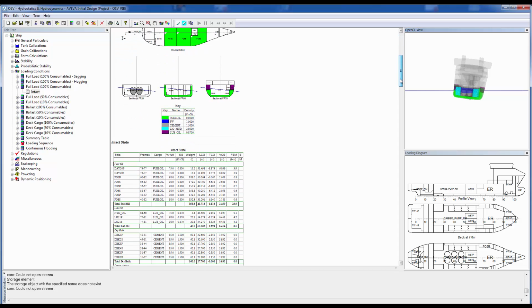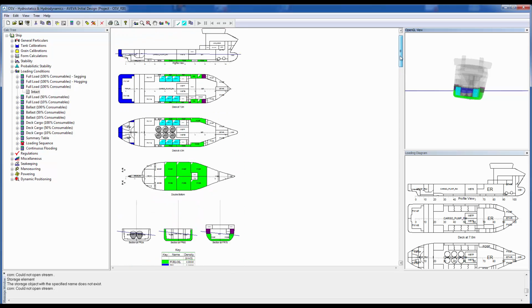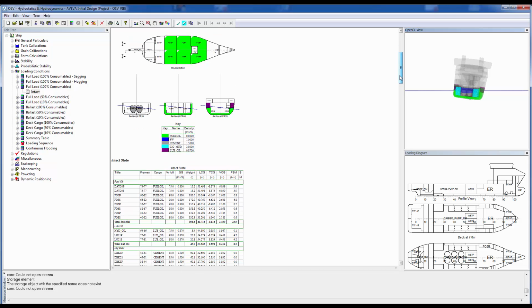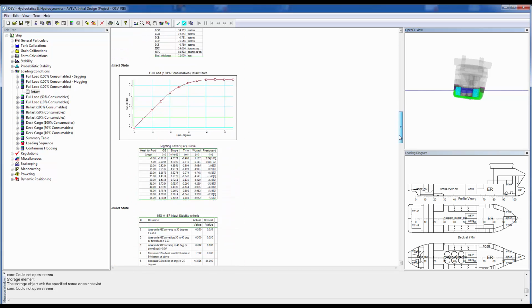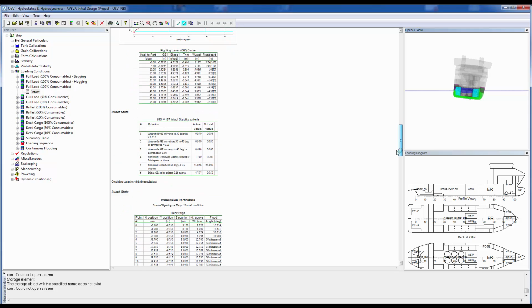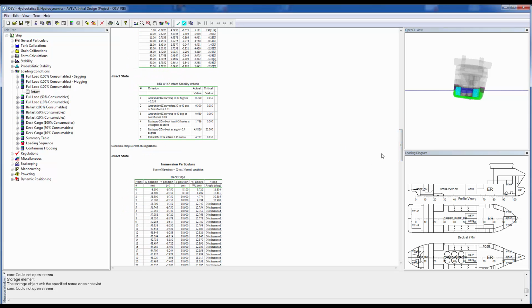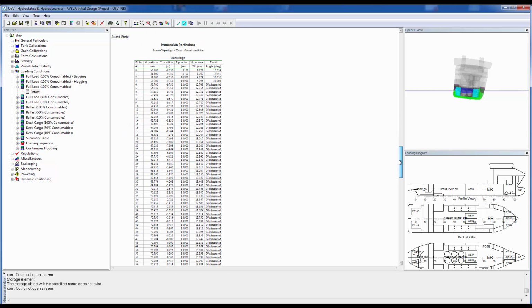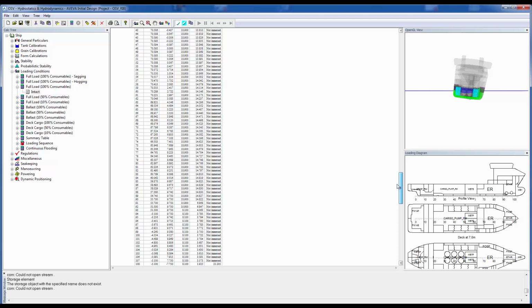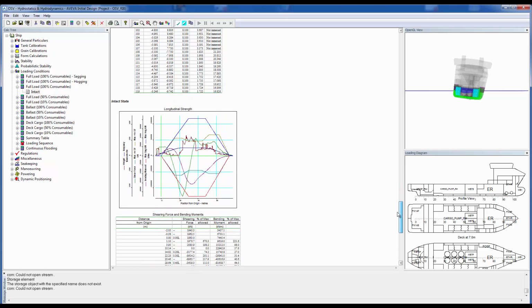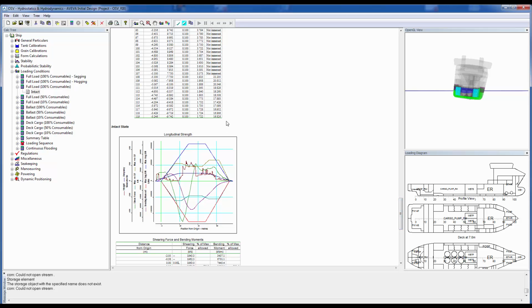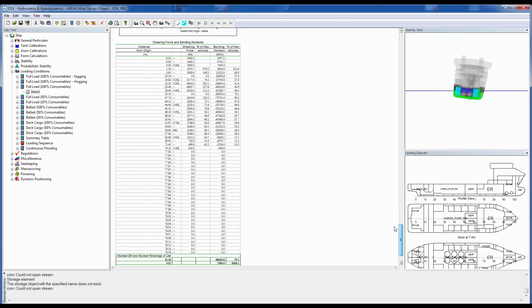So we found that the loading condition report is very much the conventional style with the plan view of the vessel, the compartments, floating position, GZ curve. We can put in the stability criteria, our points of interest. In this case here we have the deck edge, which can be reduced to 1 point for presentation purposes. We would have also our openings, and then we move on to our longitudinal strength characteristics.